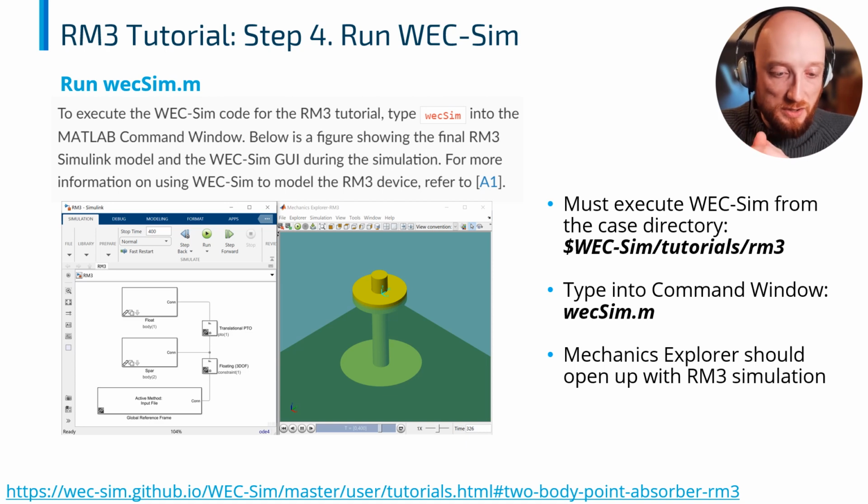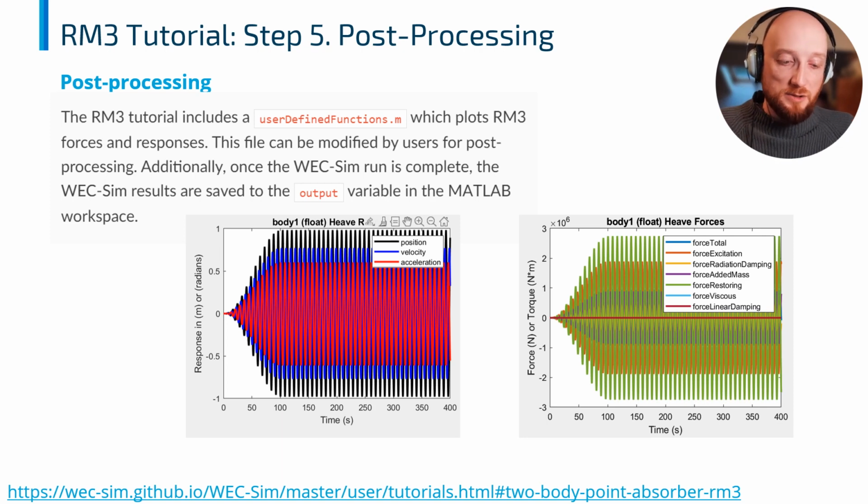But hopefully it runs for you, and you should see the Simulink Simscape Mechanics Explorer pop up, and it'll look like the window that we see here, where you see the 3D rendering of the system moving on the screen. And you can control time in this GUI, rewind it, fast forward it, and so on. Once that's finished and everything's computed, some figures will pop up showing some of the data that we've generated. And as you can see here, we're just running regular waves. You can see the kinematic data and then the forces as well acting on the system.